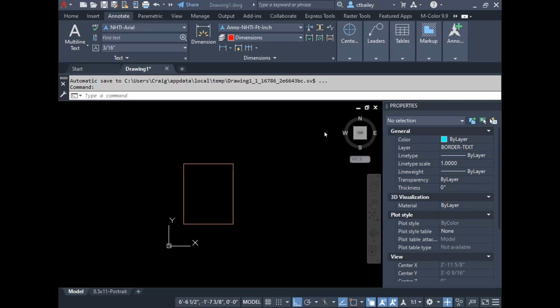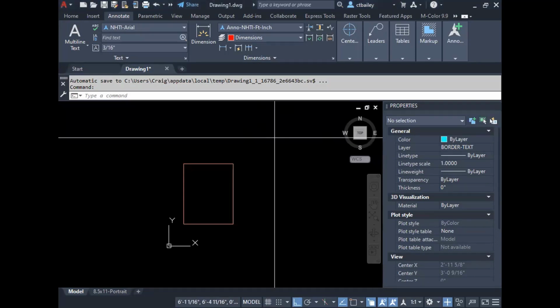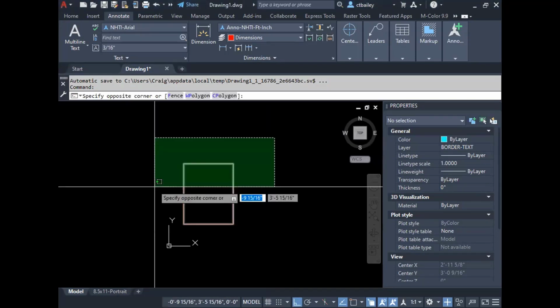To translate something in survey speak means move it, so that it's perfectly the same, but over there. Not rotated, but slid. So for the stretch action to work, pretending this is my stretch action frame, that segment will be fully translated. It'll be left alone except for its location. These two guys here will get stretched like rubber bands, cutting right there.